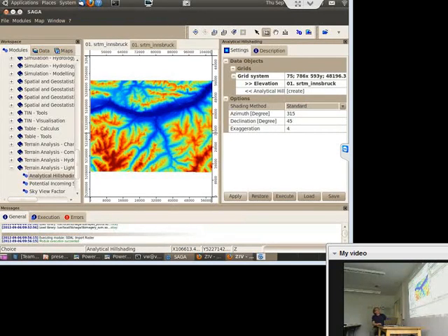One thing about these arrows: arrows pointing to the right are input data sets, and arrows pointing to the left are output data sets. Two arrows means that this is a mandatory data set. That is, you must specify it. If we had some parameters with one arrow, then it's an optional data set which you can use, but which must not be used. So once we have specified these parameters, we can execute the module,